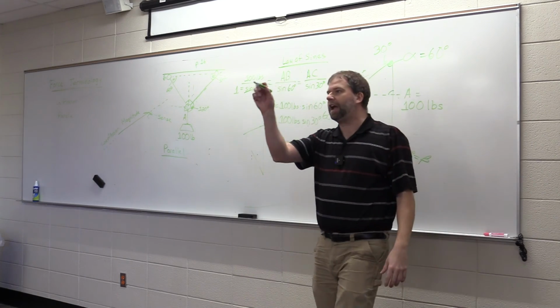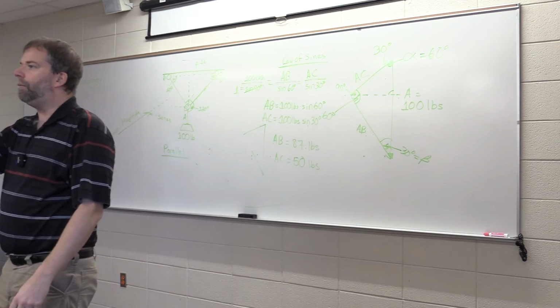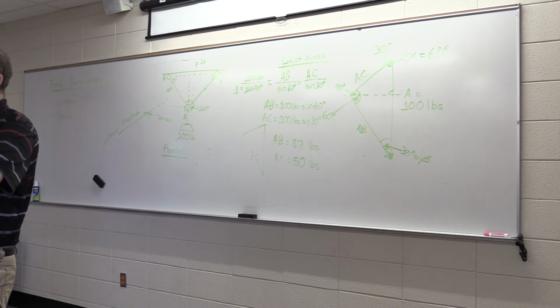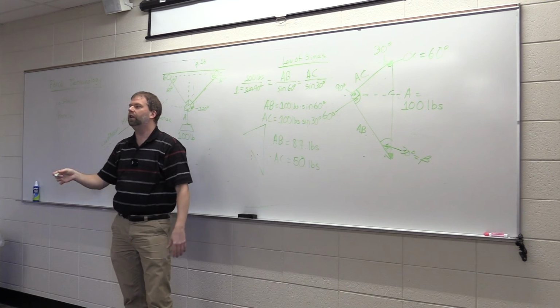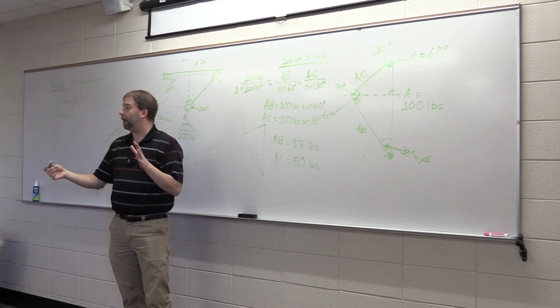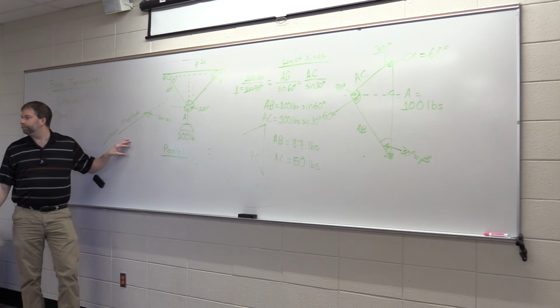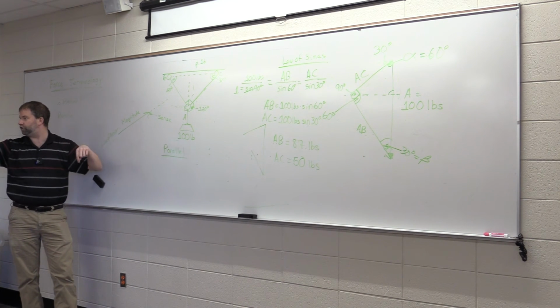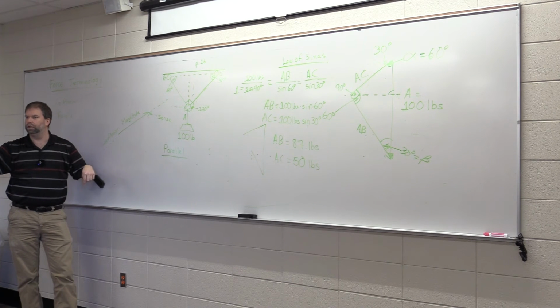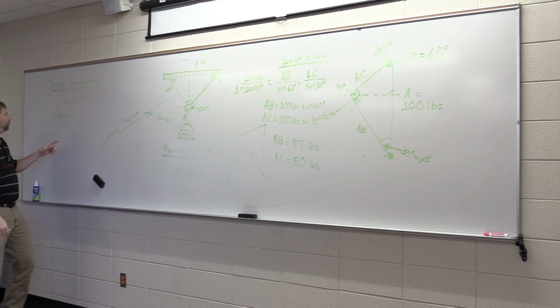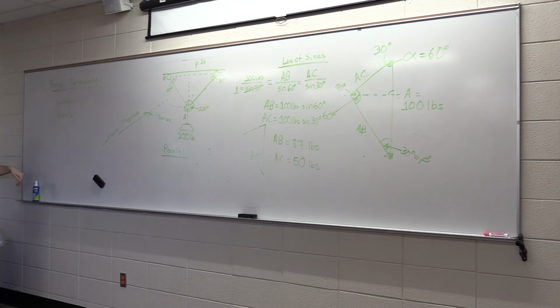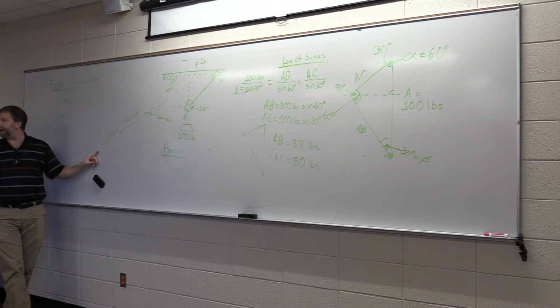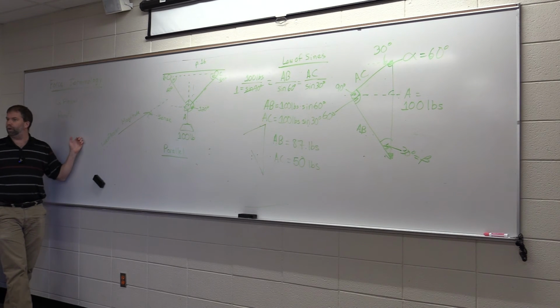If we go to the back of the room and look at the brick wall back there, and we ignore the door cut out and the effects of the forces moving around the door, let's just focus on the section of block where there isn't a door. Are those forces going to be relatively the same as the forces up here? They're going to travel in the same direction, right? With about the same magnitude. They're trying to get down into the earth. Those would be parallel, okay? Because they aren't operating in the same plane. Yes, they're moving down like this, but they have a different line of action than the forces in this wall, okay?